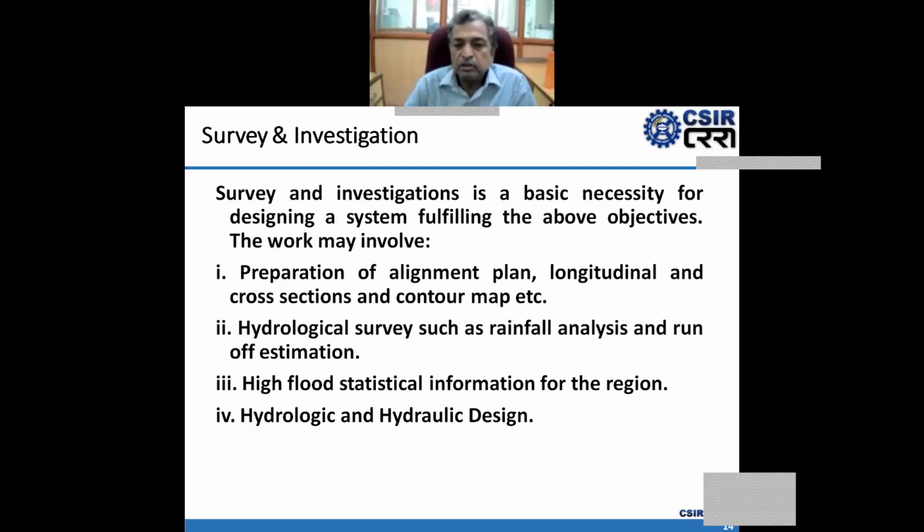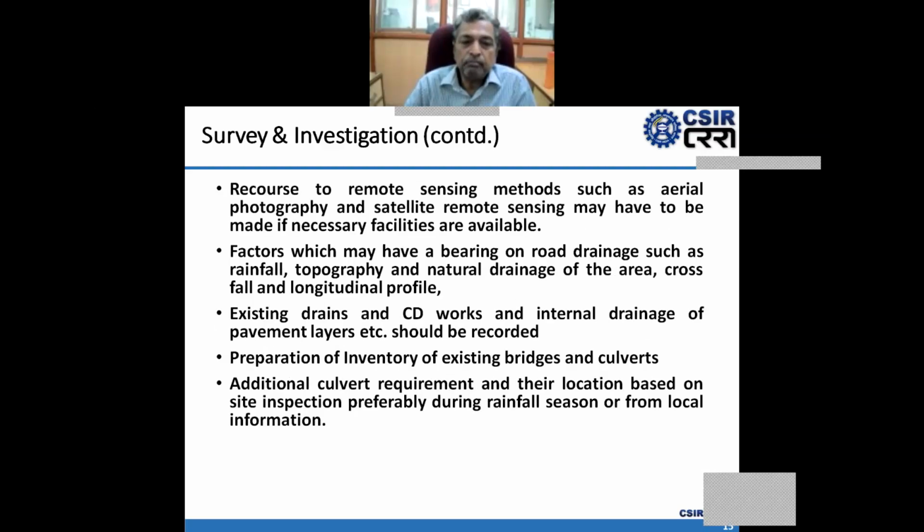Hydrological survey, such as rainfall analysis and runoff, high flood statistical information for the particular region where we are going to design the drainage system, and hydrologic and hydraulic design. Recourse to remote sensing methods such as aerial photography and satellite remote sensing may have to be made if necessary facilities are available.